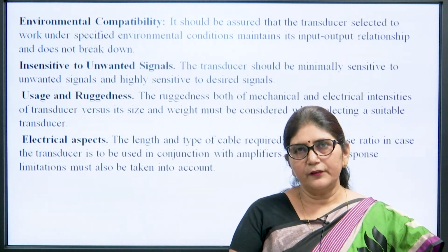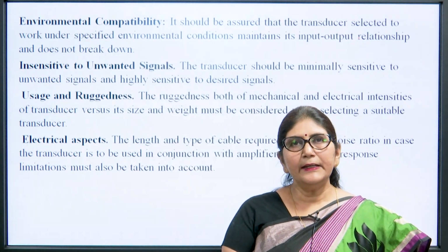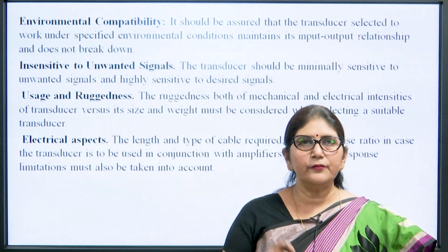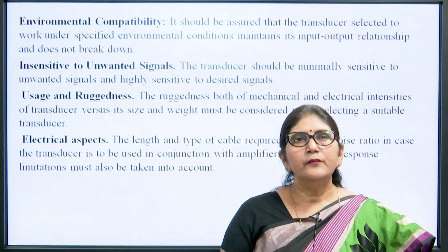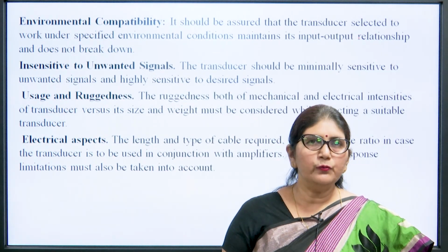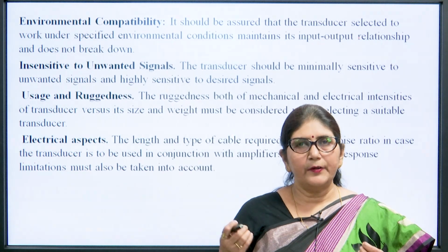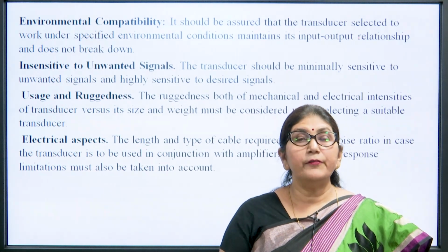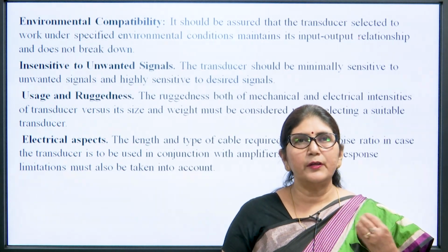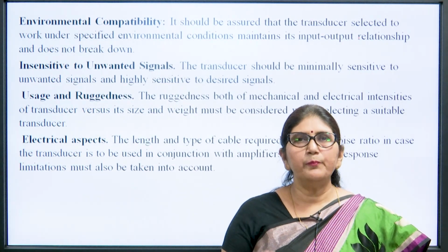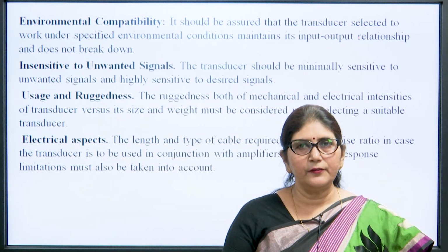Then electrical aspect, the length and the type of cable required, so that the signal to noise ratio should be less. So, whether we can use a connecting wire of high length or low length, or which type of cable or wire we can use, that is also a very important parameter while selecting the transducer.